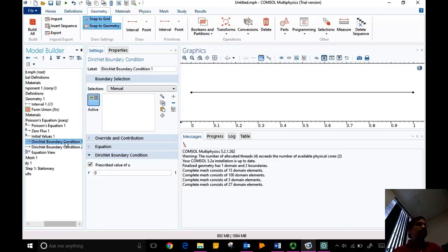So when I pick this Dirichlet boundary, currently it's empty. But if I click on the left boundary, there, it added 1. It again labels them. Boundary 1 is the left boundary, and I can give it a value here. The value is 1. Okay, and then click on the right boundary and associate it with this grid point. It's slow. And then associate it with 0. Right? Its temperature is 0.